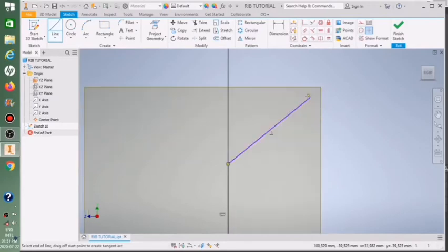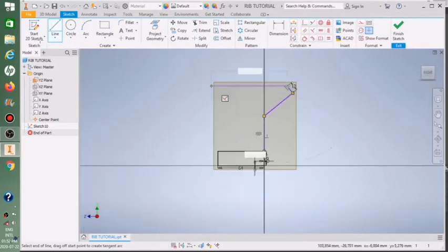And then we put it at an angle there, and then we want this line to be at 90 degrees to this line, or perpendicular, until we see a perpendicular sign. Yes, there's this perpendicular sign, and then we want it to have a thickness of 12, and then we click on enter. Yes, it's 12, and then click again the line, and then it must be parallel to this specific line. Yes, it's parallel, showing the sign for the parallel.